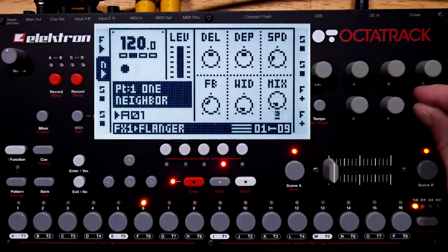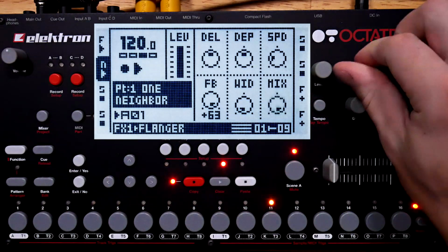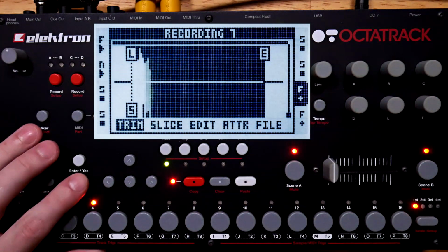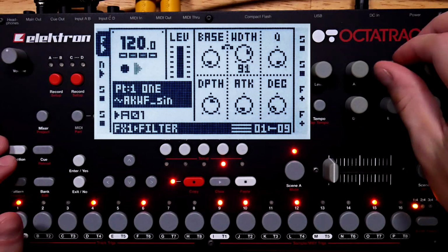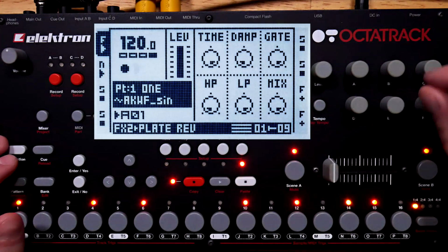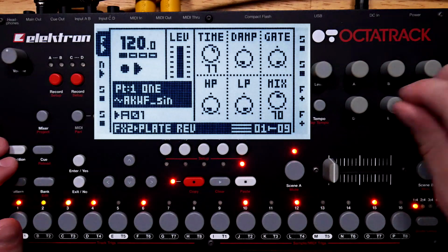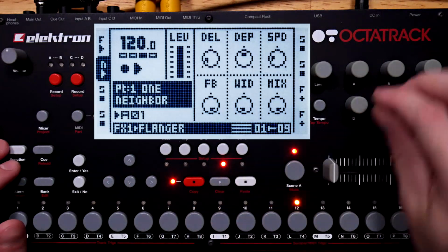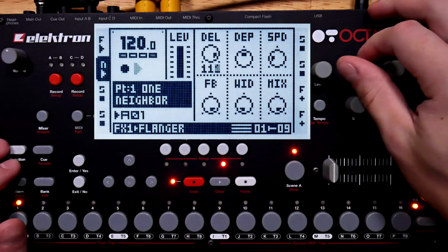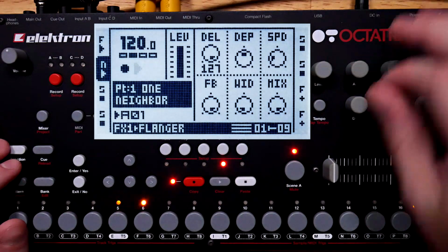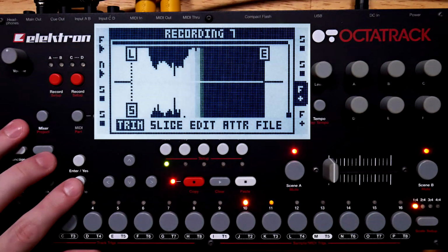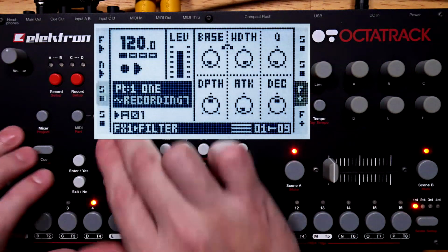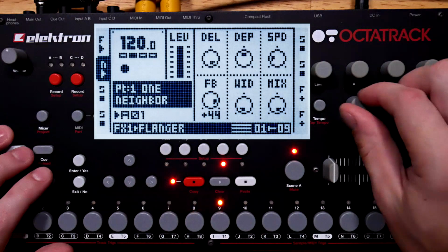With high feedback levels on the flanger and comb filter, you can end up with very high signal levels that you'll often need to tame with the compressor if you want to avoid clipping. I'm going to clean this up. Now back to that flanger. Let's see how bad we're clipping. Getting some big resonant peaks and valleys. I'll turn down the feedback a bit and take a look.